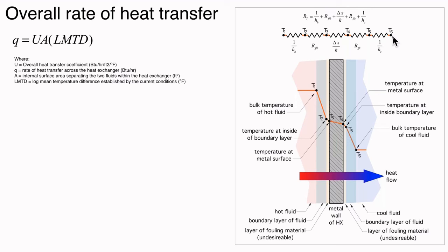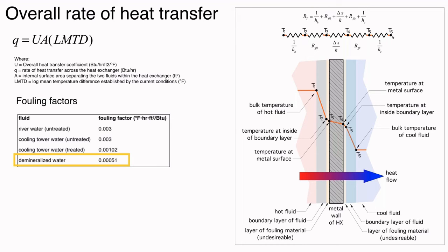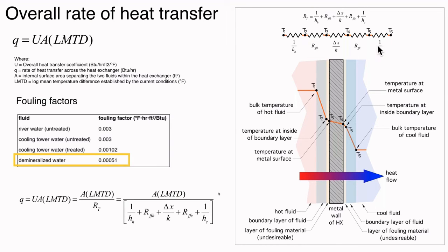And if we could calculate how much resistance effect each of those layers has, we add them together just like we'd add our values for a layer of different insulations. And that lets us determine, indirectly, the overall heat transfer coefficient here.